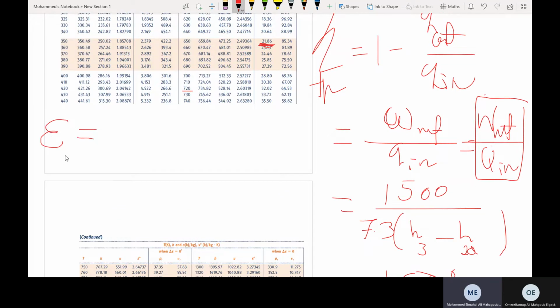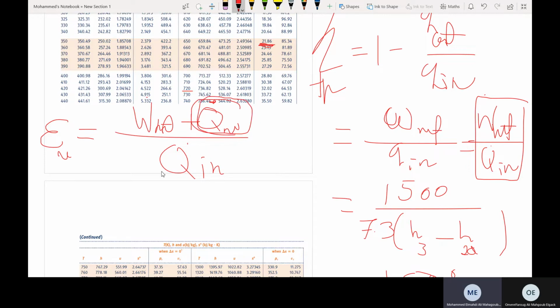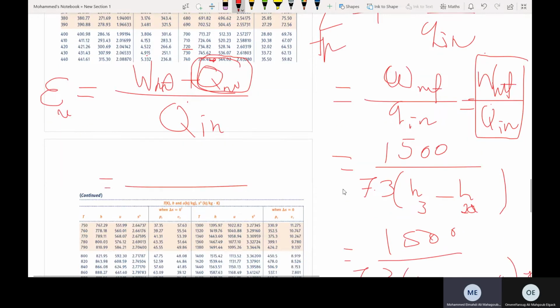It is going to be the work net of the cycle plus the utilization energy, which is the heat received by the water, or it can be the heat rejected from the turbine exhaust. You can do both because they are the same, over Q dot N. Of course, we are going to add this number to the work net, so the efficiency will increase.